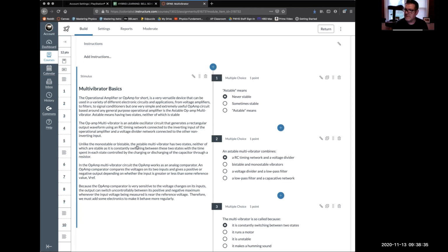I don't know if any of you have seen what's known as a drinking bird. It's a fun little toy apparatus. They make it actually look like a bird, but the fact that it looks like a bird is irrelevant. You put a glass of water there, and it dips down into the water, and then it goes back again, and then it will go back and dip again. The reason why is that at the other end, there's a bulb that is moistened with water that is evaporating. Through a process of absorption and evaporation, which is in a very, very close equilibrium, the drinking bird goes back and forth. Well, that's what our multivibrator does. It has two states of being that are very, very close to each other, and it can flip-flop back and forth between those two things.